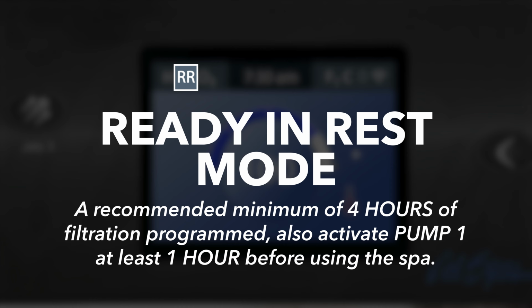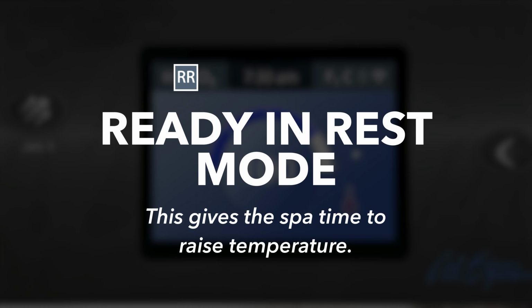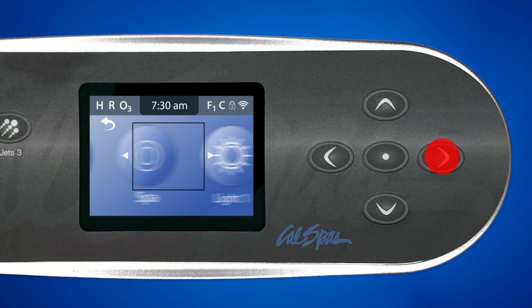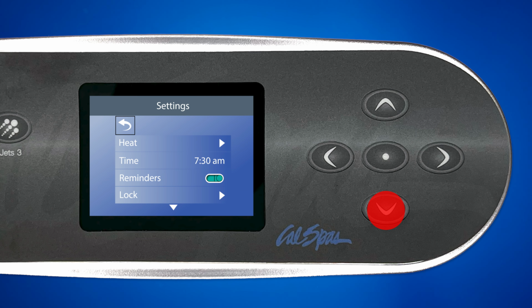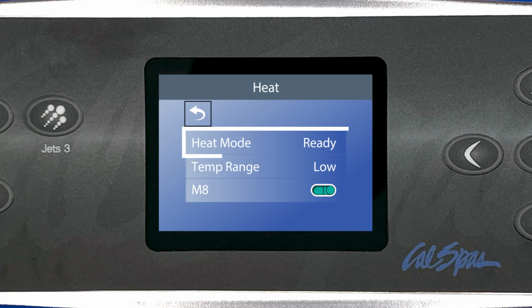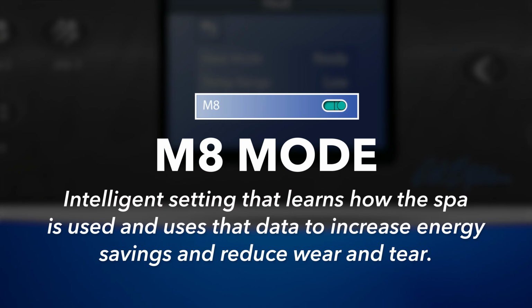We recommend in this mode to keep a minimum of 4 hours of filtration and to press the Pump 1 button at least an hour before you intend to use the spa to give the spa time to raise the water temperature. This setting can be changed at any time through the same heat sub-menu inside the settings menu, and the heat mode will be displayed in the top banner of the main screen. Additionally, M8 mode is an intelligent setting that learns how the spa is used and uses that data to increase energy savings and reduce unnecessary wear and tear in the spa's components. We recommend leaving this on.